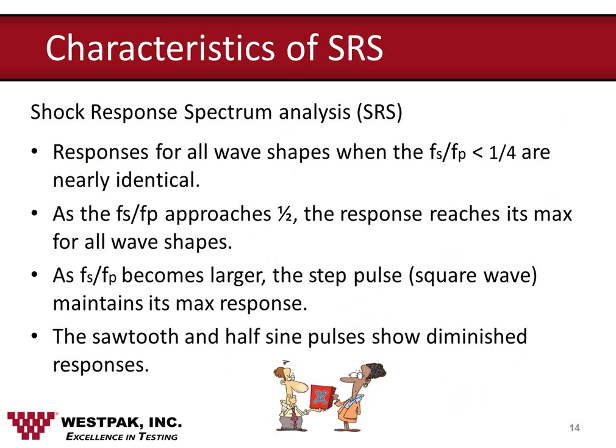Here are the things that we should remember from this brief dive into shock response spectrum analysis. Regardless of the wave shape, when the duration of the input is very short relative to the natural period of the response, the response is only a function of the velocity change of the input, not of the wave shape, peak amplitude, or anything else. The velocity change is the area under that acceleration versus time pulse. It can be thought of as the energy content of the pulse, although it's not really energy because there's no mass involved in it.